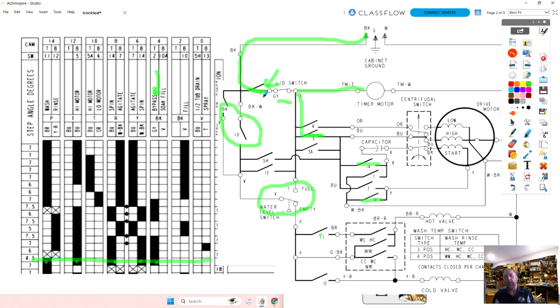Does Whirlpool, the older washers, the direct drive, use a lid lock? No. So why on some manufacturers do we use a lid switch and on another a lid lock? Both of them, we put those switches in for safety, because when a machine is spinning so fast, we do not want a customer to be able to open the lid.